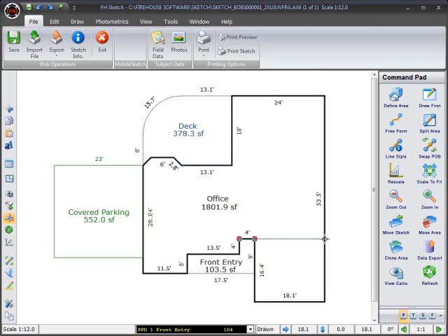Now I need to move to a new location to begin a new line. I'm still in a drawing state as indicated by the crosshair cursor. If I press Enter again without drawing anything, the cursor will change to a pointer. This is what we refer to as picking the pen up. I need to move the cursor 13 feet up from here to draw the next line. I'll enter 13 and press the up arrow. To put the pen down again, I'll press Enter, which changes the cursor back to a crosshair. The line I need to draw is 12 feet to the left, so I'll enter 12 and press the left arrow key. Now I'll press Enter to anchor the line.